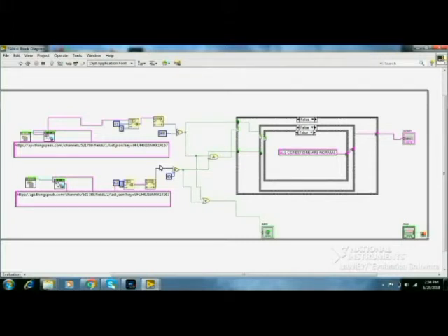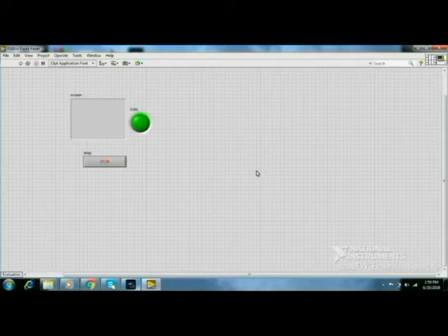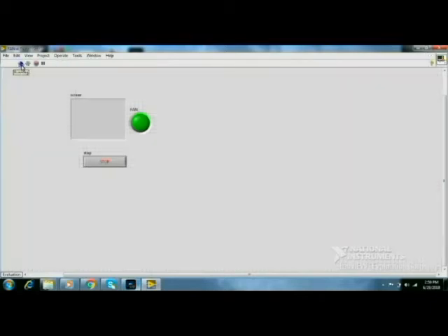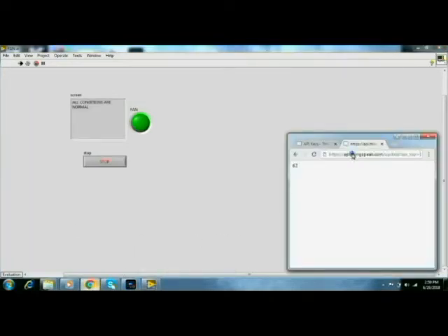Now let's see this work. We are changing the value in ThingSpeak by using a web browser. Let's run this by clicking the run button. We're going to open the browser and change the value in ThingSpeak Cloud. First, I'm going to give a fault value, say 90. As the RPM is set to 90, we see the field value is updated. As the field value is updated, we can see the alert message is printed over there. Now, I'm going to give the correct value and change this back to normal.